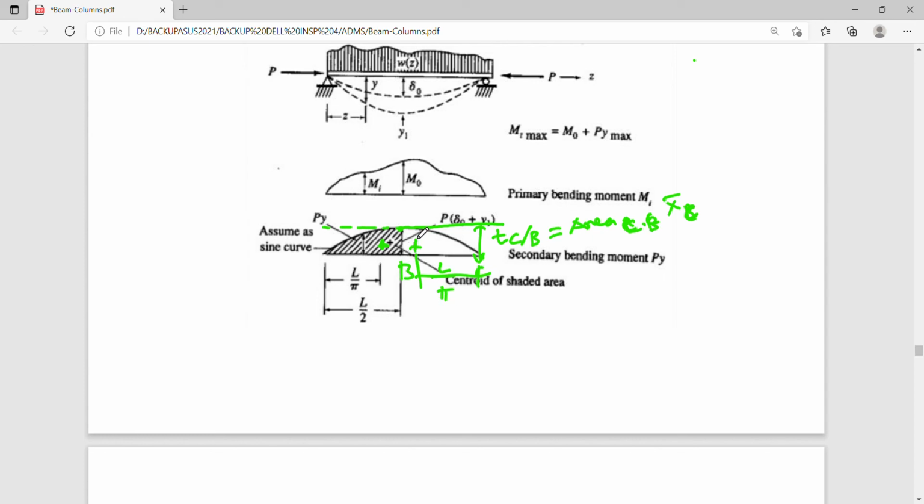So this is a sine curve. Remember that this is a sine curve. The sine curve has distances taken as periods. That's why you have a pi there. So these are angular values. That's why there's an angular term in radians here. So you watch the areas, the area of a half sine curve. We're only taking one half because the tangential deviation is only from B to C.